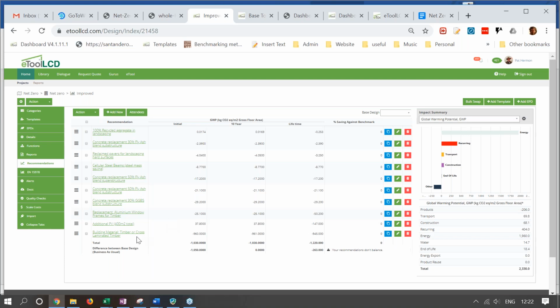And some really significant savings, if you're really going all out, come from looking at timber. Timber is essentially a zero carbon material in most circumstances, certainly in most building circumstances. Here we're saving a whole ton per meter squared, near 900 kilograms per meter squared, a whole £100 per meter squared saving in the offsets. Timber may have an increase in cost.